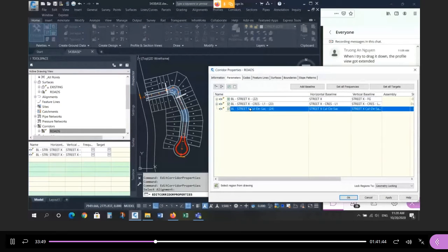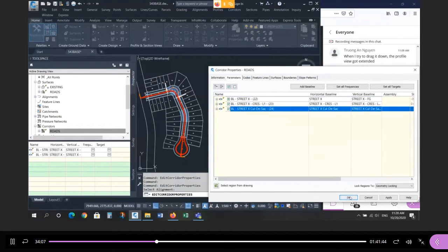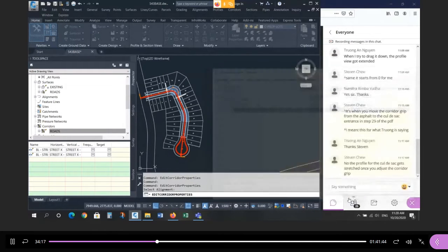So to add the region, you right click and you say add region. And that's where you add the cross section. And what you want is the crescent with the boulevard on the left side. Okay, so I'm going to reuse that one because I strategically chose 0 on this side to go around this way. Say OK. Let me build what I've done so far so you can see what you have to fix. Okay, you don't have to stop and start the way I am. I just want you to see the effect of the different functions. Okay, so I'm just going to add those 3 pieces and let it go.